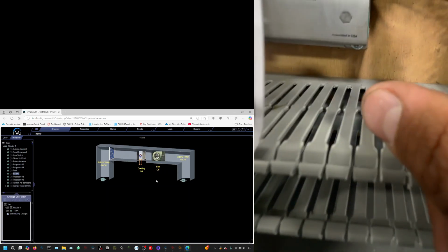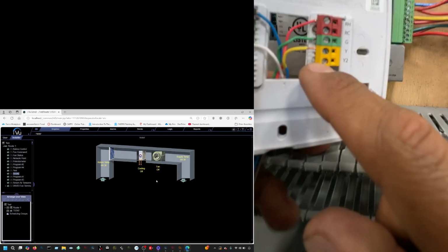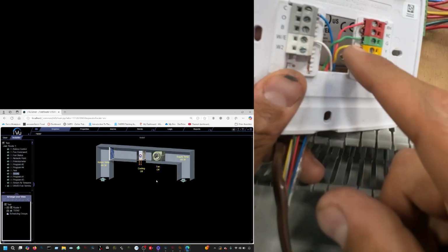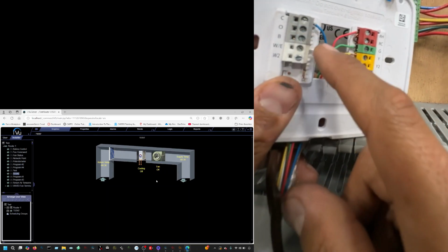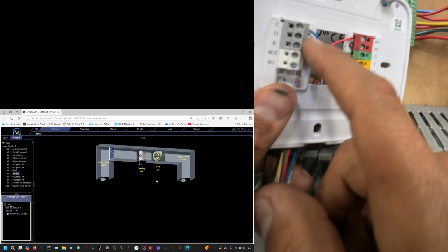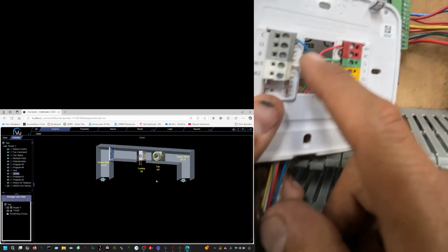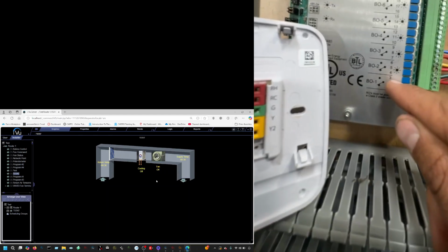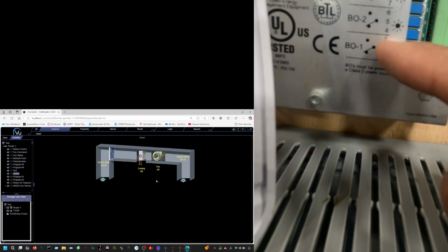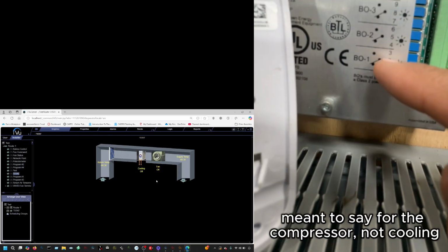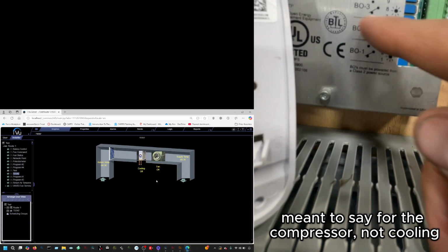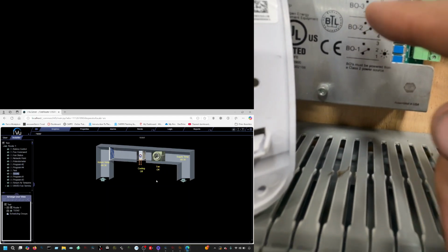Okay. So the wires, like for example, this Y and the O wire, I know I don't have anything connected here, but let's pretend it's just an orange wire coming out of the O. Those are gonna go on 3 and on 6. I'm gonna use binary output 1 for cooling, binary output 2 for the reversing valve.